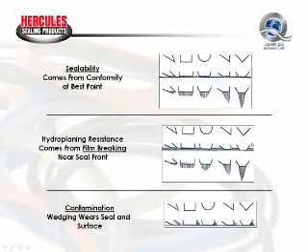Well, there are some applications where actually you want a heavier film of fluid on the surface to be sealed. One of those would be in a pneumatic cylinder application because there's a lot of money spent to atomize fluid into the pneumatic system to lubricate the internal components of cylinders and to help reduce rust and so forth from moisture that gets into pneumatic systems.